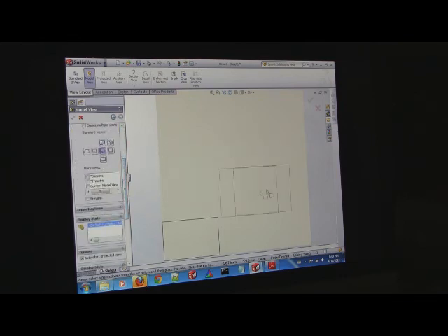Now, move your mouse into the middle of the screen and you'll see it's got kind of like a blank box. See that? Everybody should be wiggling a blank box. That's incredibly frustrating because there are many different views that I could have. I could have isometric at an angle. I could have orthographic at different faces. So what you do, see over here, there's a preview. Press the preview button and now it shows me what it wants to draw. Okay? So now it's easier.